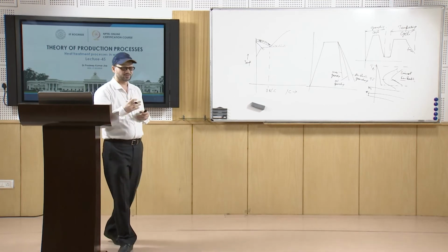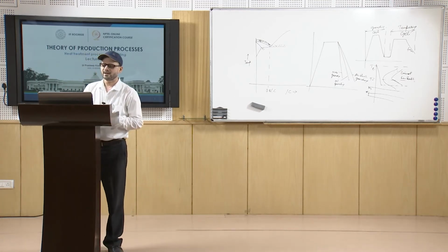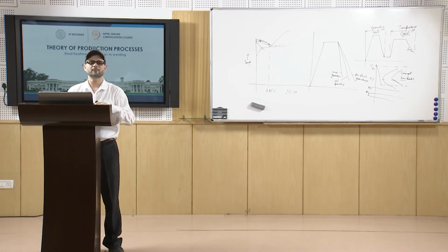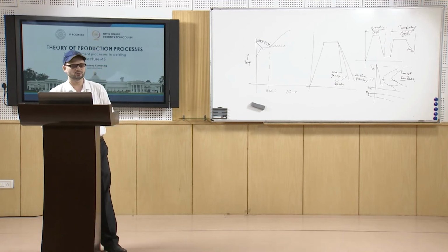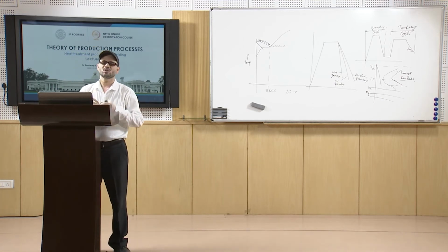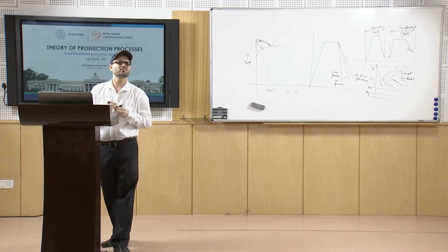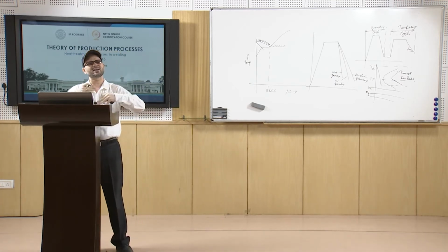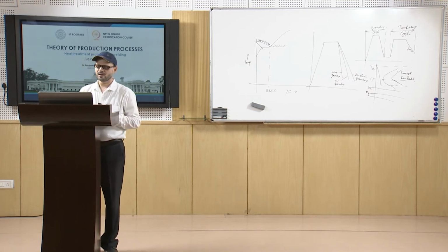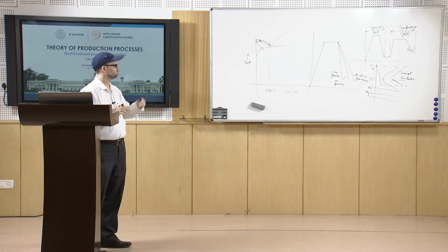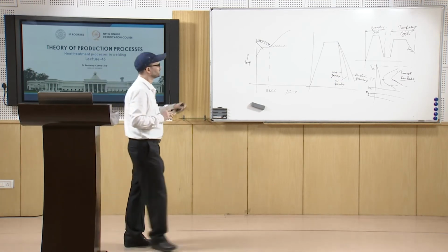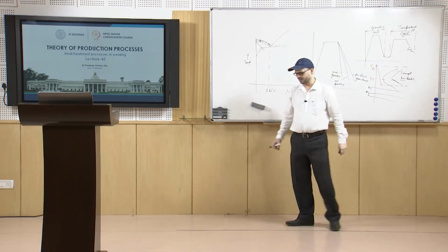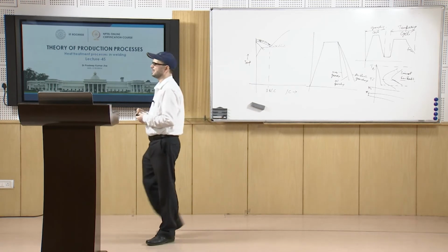In austempering you get a bainitic structure, and quite good hardness and toughness is obtained. This is one of the very important heat treatment processes, used whenever we need a bainitic type of structure. You take the austenitic structure and temper it. Austenite is tempered, so that is why it is known as austempering, and that is how you get the bainitic structure.